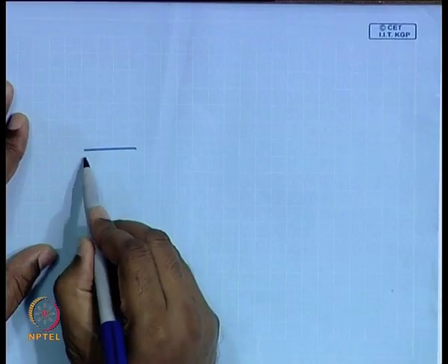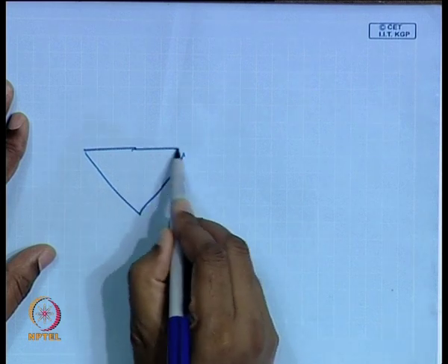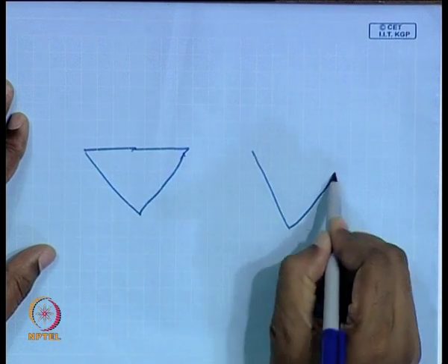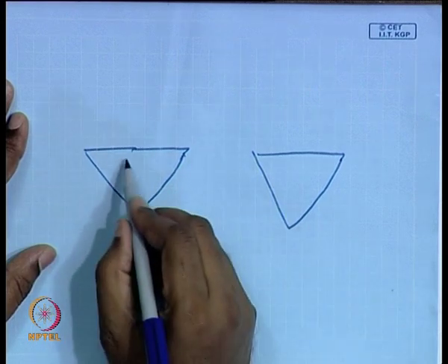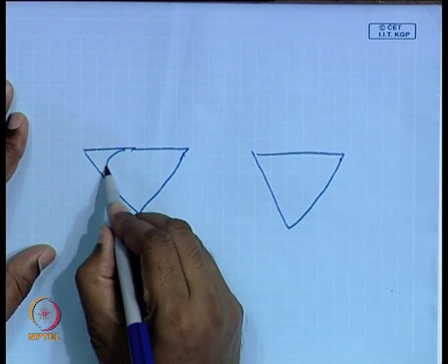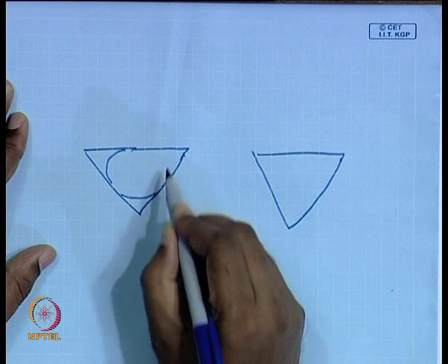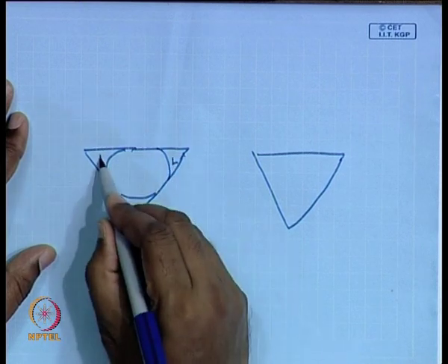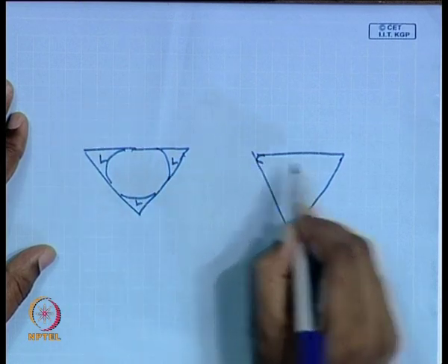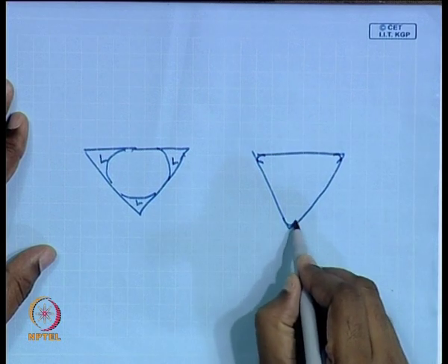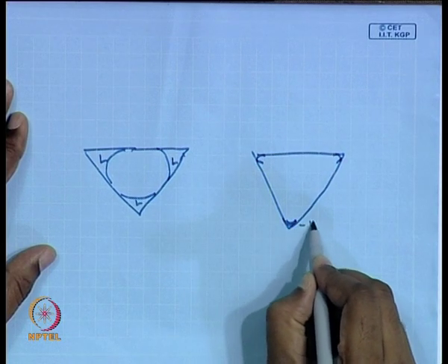There are other limitations of heat pipes as well. Now, if you think of a heat pipe in the hot and the cold zone. In the cold zone, the heat pipe is like this, with this portion filled up with liquid. In the hot side, only the corners have some liquid left in it.